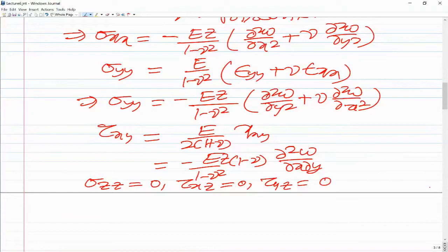So we are assuming an approximation of the displacement along the thickness direction. So u and v are linear in z and w is constant along z. So we are reducing a three-dimensional problem to a two-dimensional problem using classical Kirchhoff plate theory.